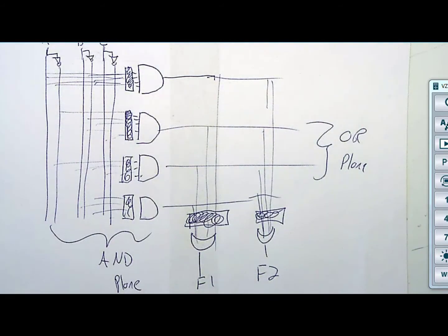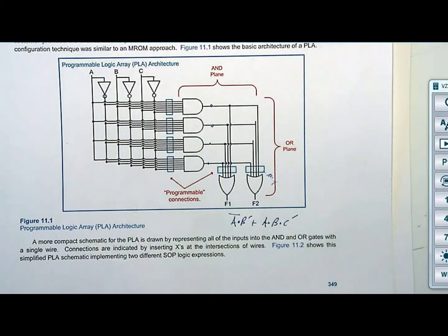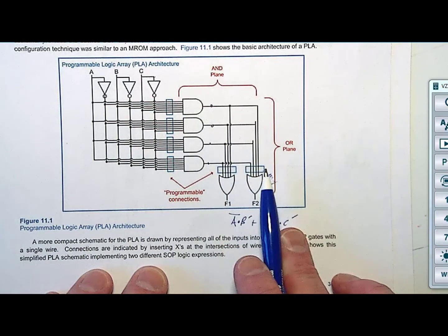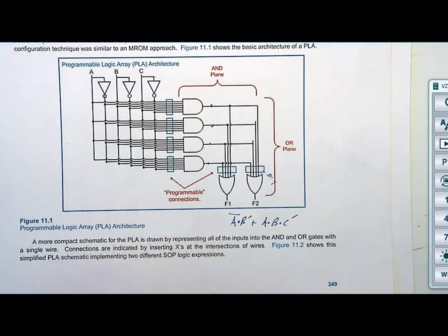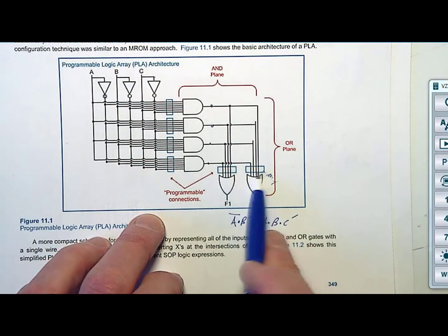Well, it turns out that if you look at this, you've put a whole lot of stuff down in order to implement everything under the sun. Namely, one of the things that sucked about this is that you had all these interconnections for these OR gates, and it started adding a lot of delay. You had a lot of OR gates consuming power. You had a lot of metal running every which way. You had to have the capability to connect these during fabrication.